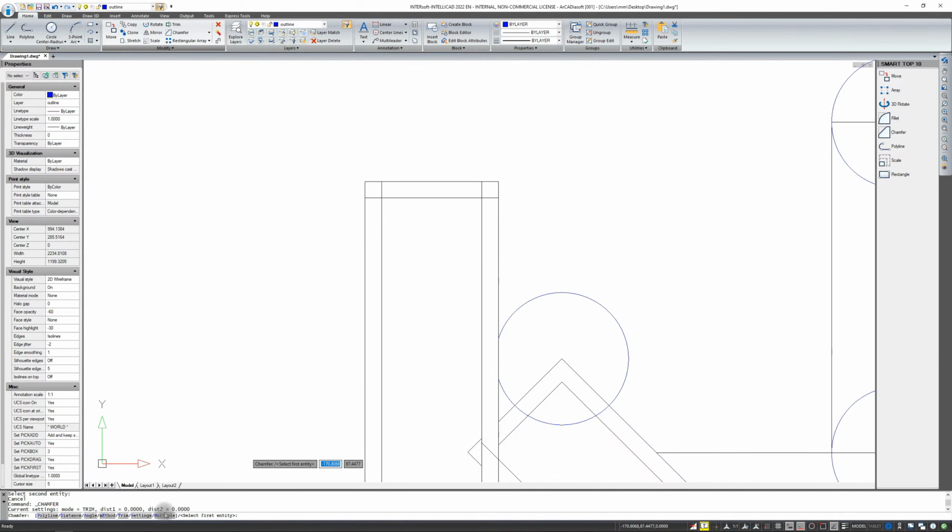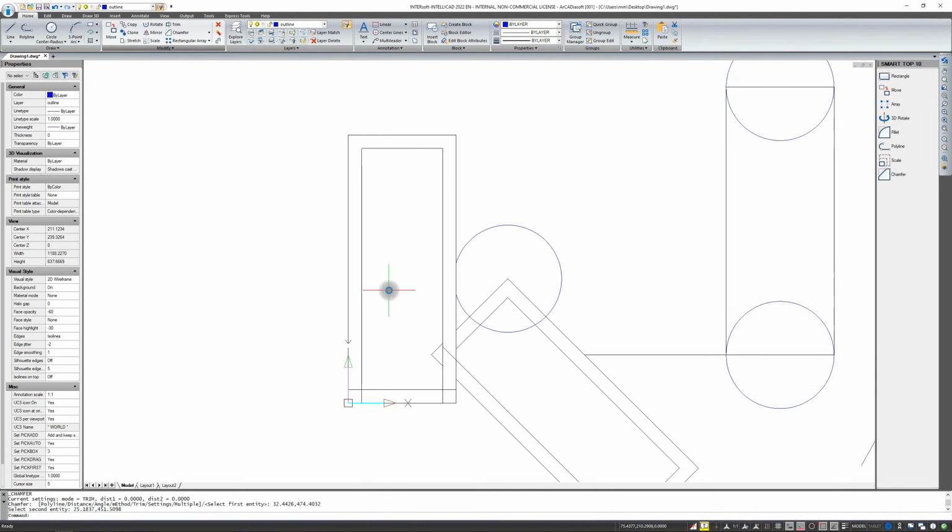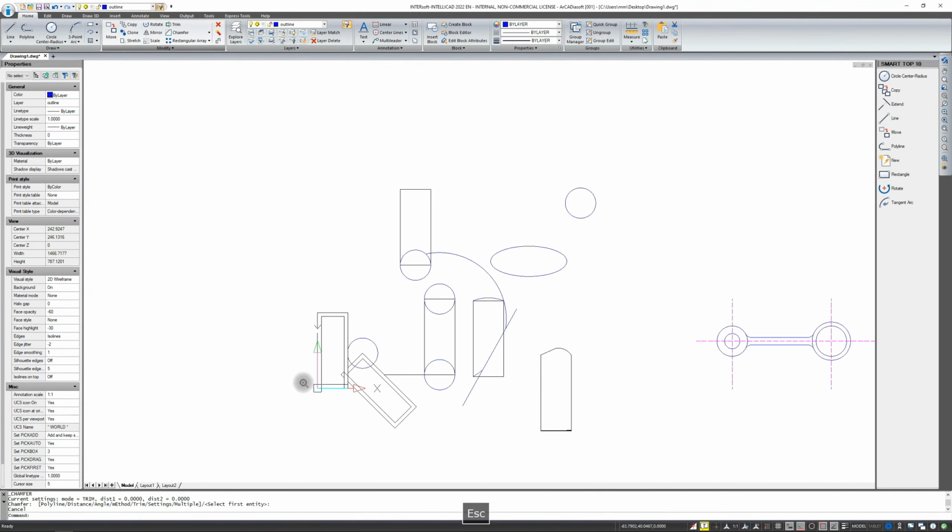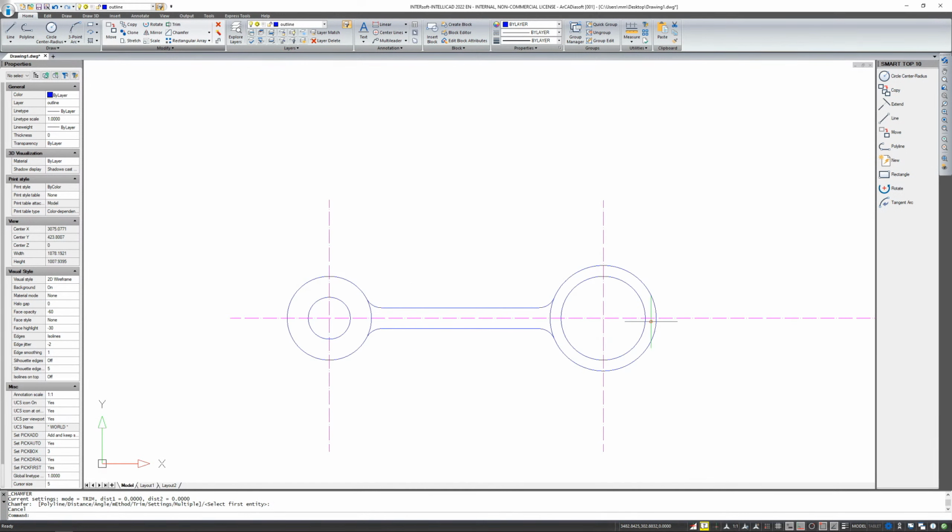Please note at the bottom in the command area, I have information that on both sides 0 units are entered. So this cut will not be there. It means that it is just shown that these two elements and they're automatically cut to each other. So I do not have to enter the cut option several times and show these individual elements separately to be cut. So chamfer can cut corners and, for example, lengthen or shorten, as long as you have properly defined the settings. When you draw, a function that is frequently used is rotate.